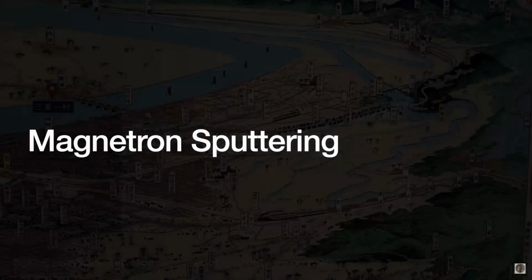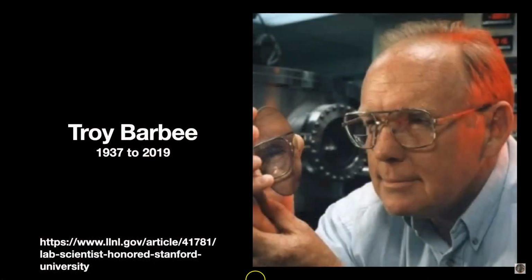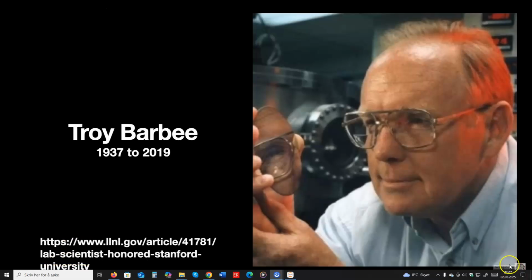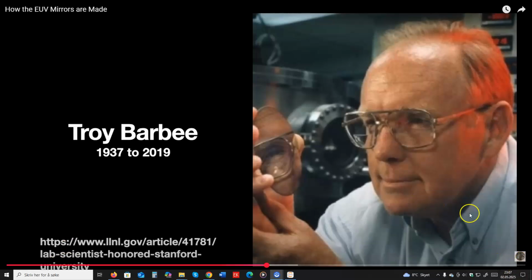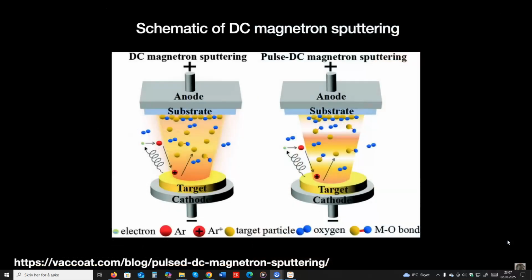In 1978, Spiller met with Troy Barbee at Lawrence Livermore National Lab when the latter gave a presentation at a Stanford workshop. The two got to talking about the potential of making multi-layer reflection mirrors with a process known as magnetron sputtering. Sputtering refers to a process where atoms or particles are ejected into a vacuum after bombardment with high energy particles or ions. Then the ejected atoms can be made to settle onto a substrate.